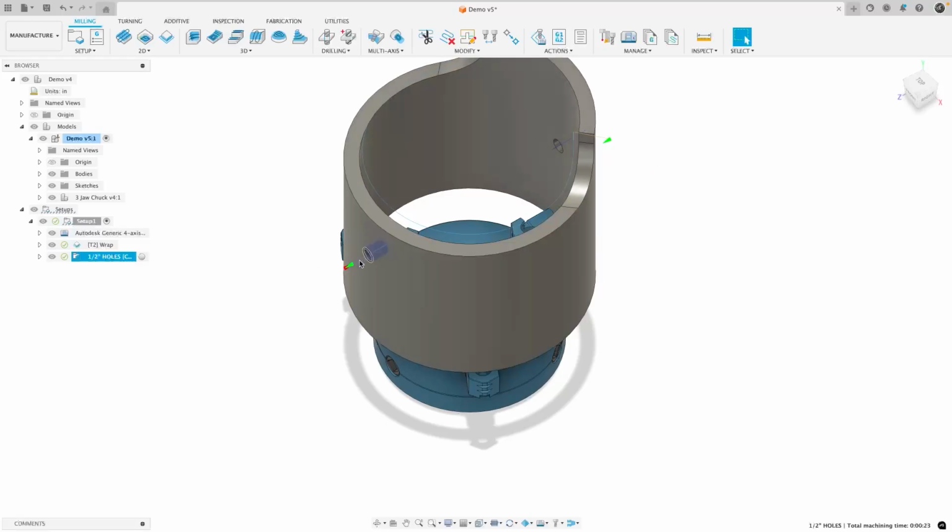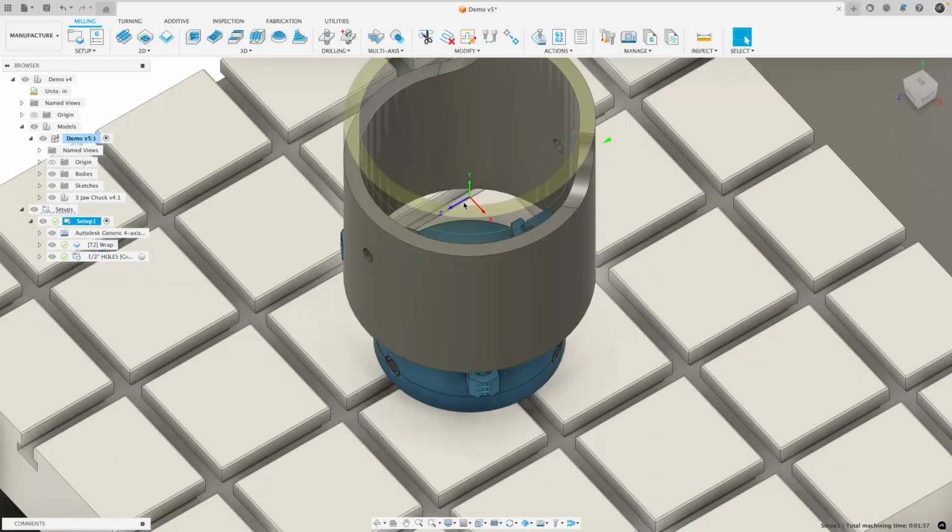On B0 on this first hole, it's not a problem because on the machine coordinate, since we already have B0 set here and this hole's already there, it won't try to output G68.2. This appears to only happen on the drilling cycles, and there is something we'll have to disable on the post processor.